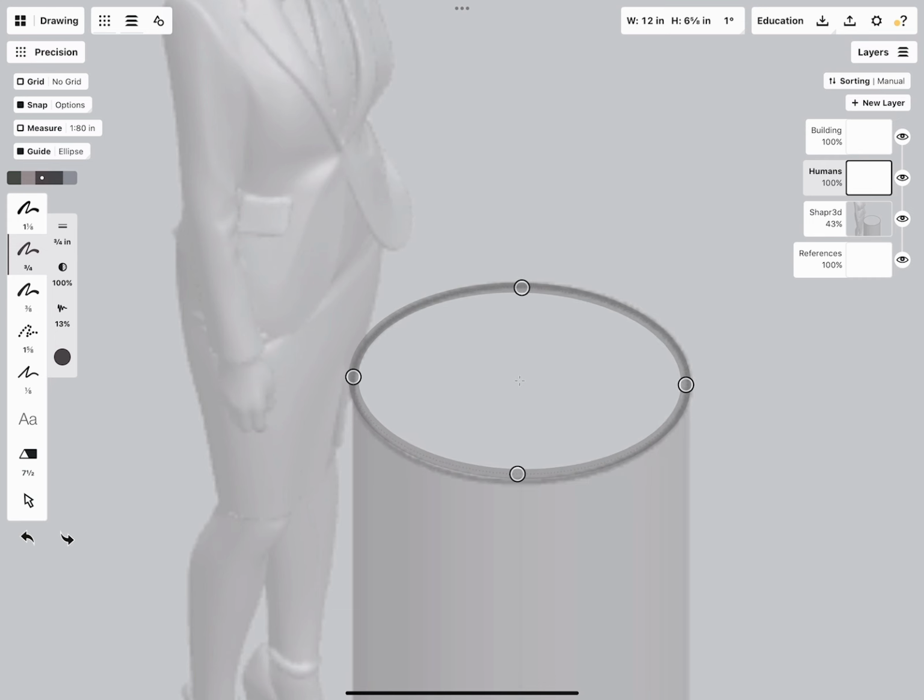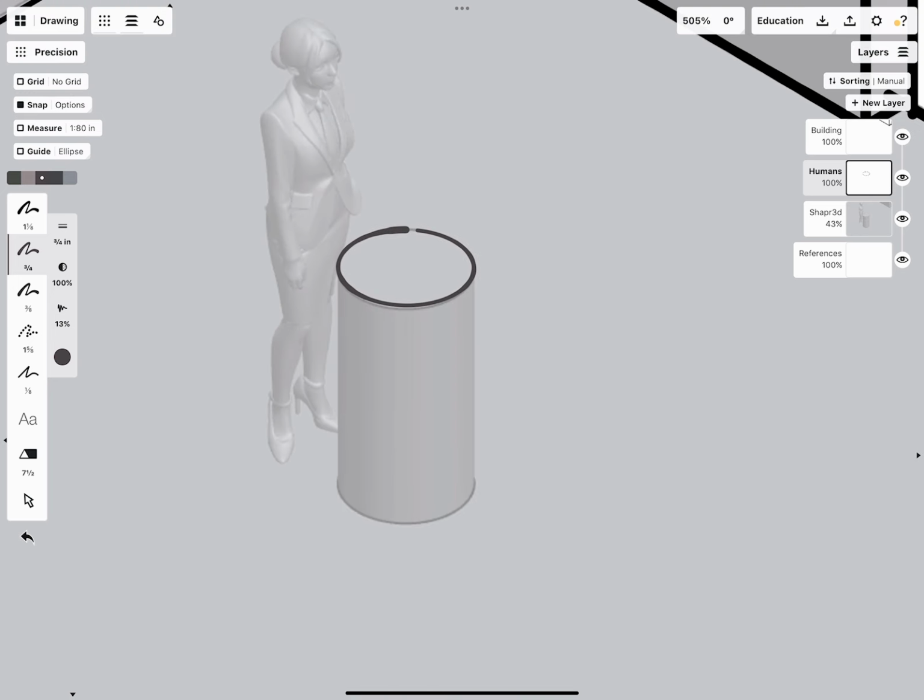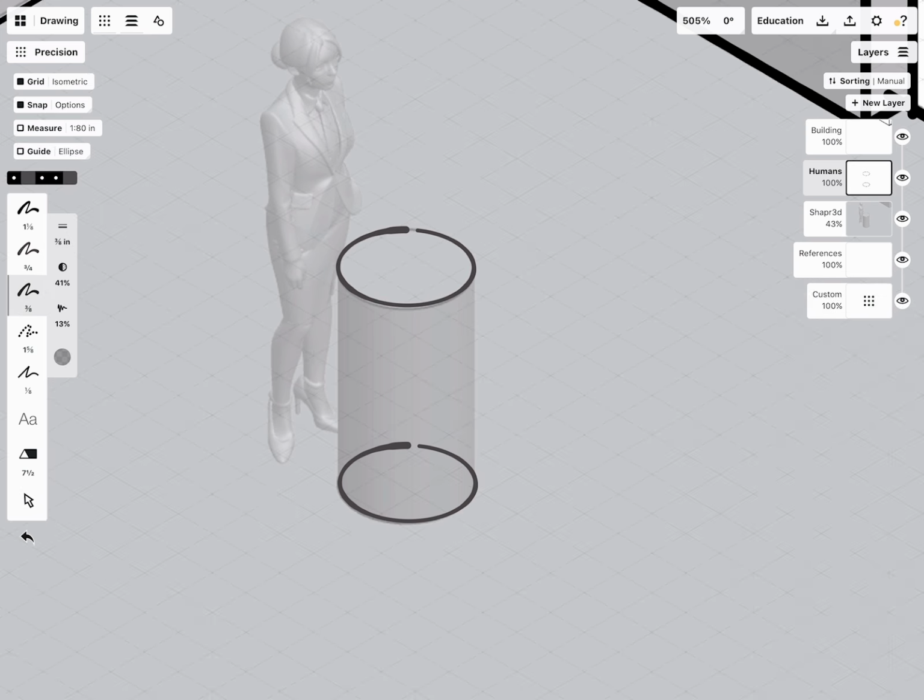This point has to go to there, and these have to be horizontal and isometric. Cool. And then I can simply draw over it, and there's my really nice ellipse. This one I could select, make a copy, bring this down to there, go here. Actually, then that might be again a moment to, if I want to, turn the grid actually back on.